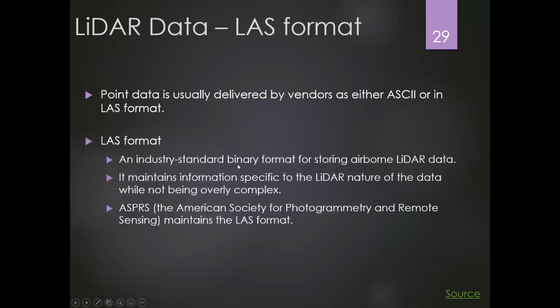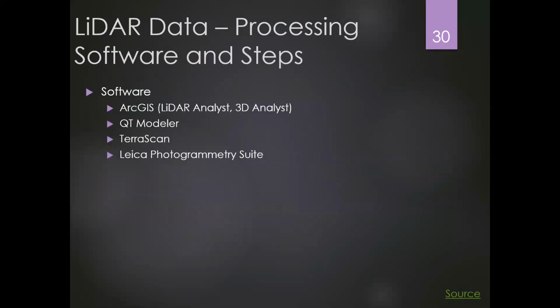It's an industry standard binary format for storing airborne LiDAR data. So it is not for a specific company or enterprise. It is a commonly used format. It maintains information specific to the LiDAR nature of the data while not being overly complex. This format is maintained by ASPRS, and it is free, so everybody can use it. And we can use different software to deal with LiDAR data.